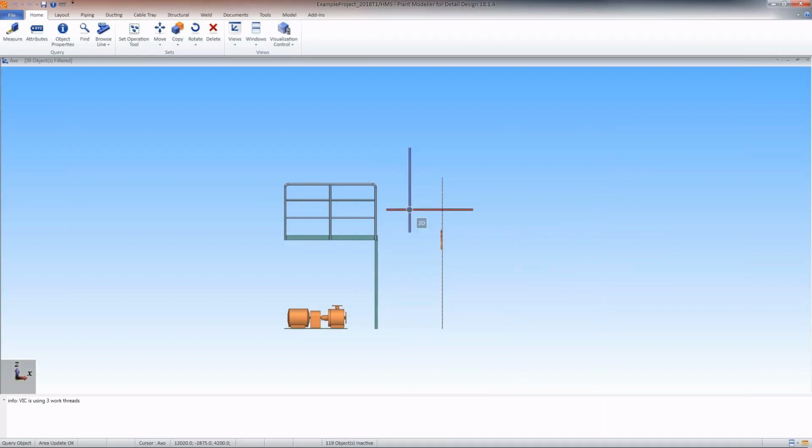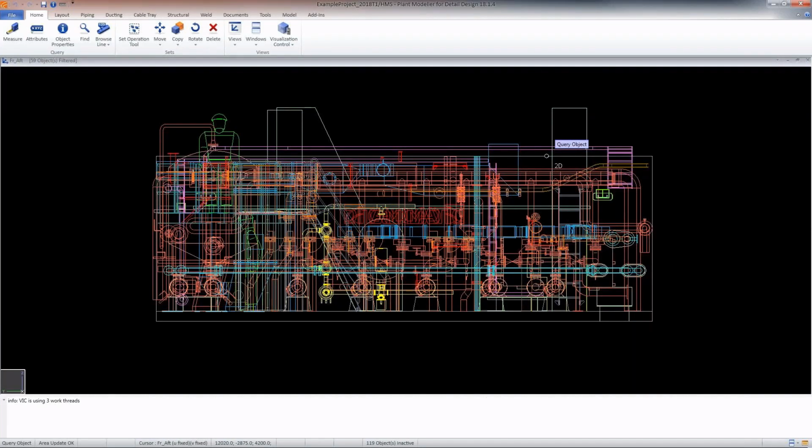And unlike the Edit Filter Box command, this new functionality also works in wireframe views. In this wireframe view, I can limit any face or corner, and here the larger box is our front plane, while the smaller box inside it is our back plane.